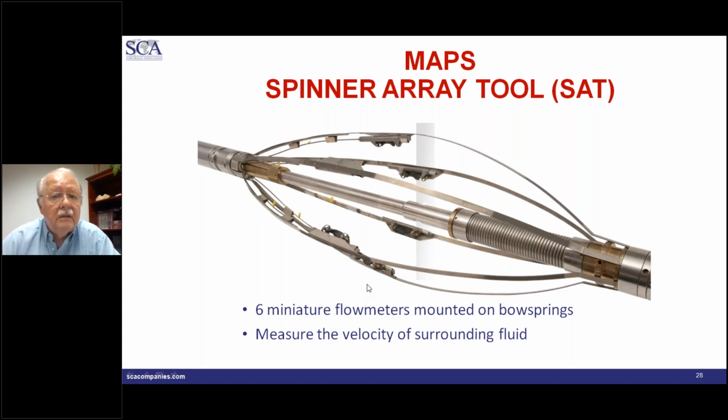The other tools that the Sondex has and General Electric now is they have a tool called a RAT, resistance array tool. So we have a spinner array tool here, resistance array tool, R-A-T on the tool string. The resistance array tool is very, very similar to the DEVT. It has a resistance probe on it and can discriminate water from hydrocarbons generally. And then lastly, there's a tool called a CAT, capacitance array tool. That capacitance array tool can discriminate, I think, all 3 phases, but it's a fairly large diameter tool, and it cannot, in general, discriminate very tiny bubbles and stuff.